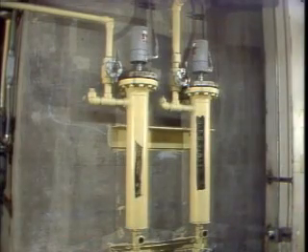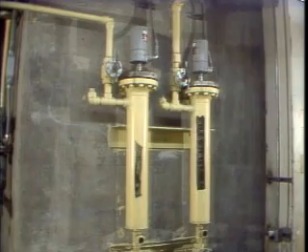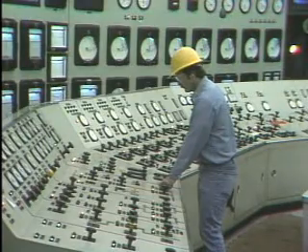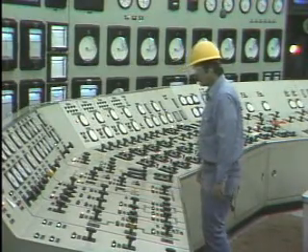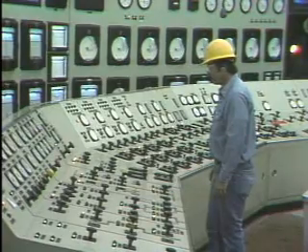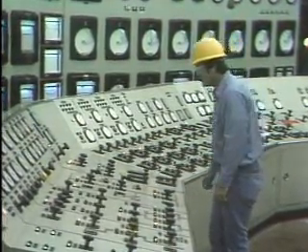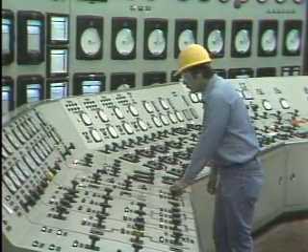Operators can examine a device called a liquid detector to check for water inside the generator. No matter how it's detected, a leak in the hydrogen cooling system means that the operating personnel must follow plant procedures to take the cooler and possibly the generator out of service so that repairs can be made.